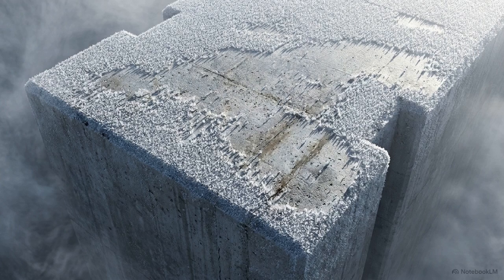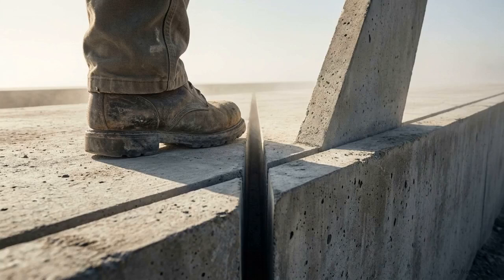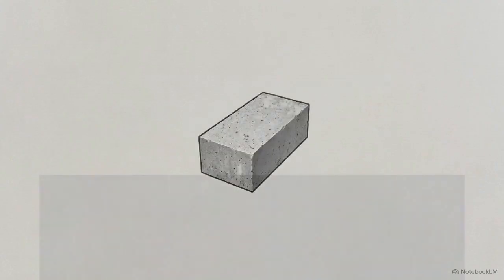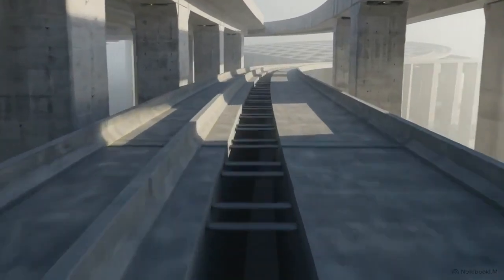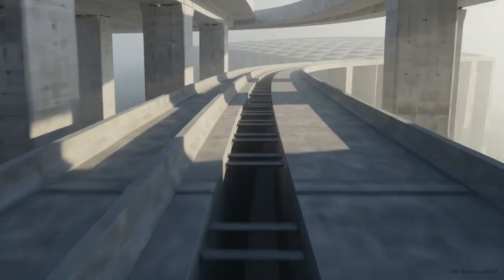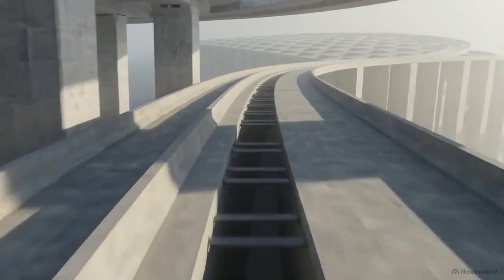To counter the opposite forces, dropping temperatures and the natural shrinkage of curing concrete, engineers deploy transverse contraction joints, often called dummy grooves. By cutting a groove only 1/3 to 1/4 of the way into the pavement depth, engineers create an artificial stress concentrator. When the concrete inevitably shrinks and tears, the crack is forced to propagate straight down from the tip of the cut, neatly hiding the fracture beneath the surface. Transverse joints handle the dominant longitudinal shape changes of the highway, dictating the safe geometric boundaries of the slab.